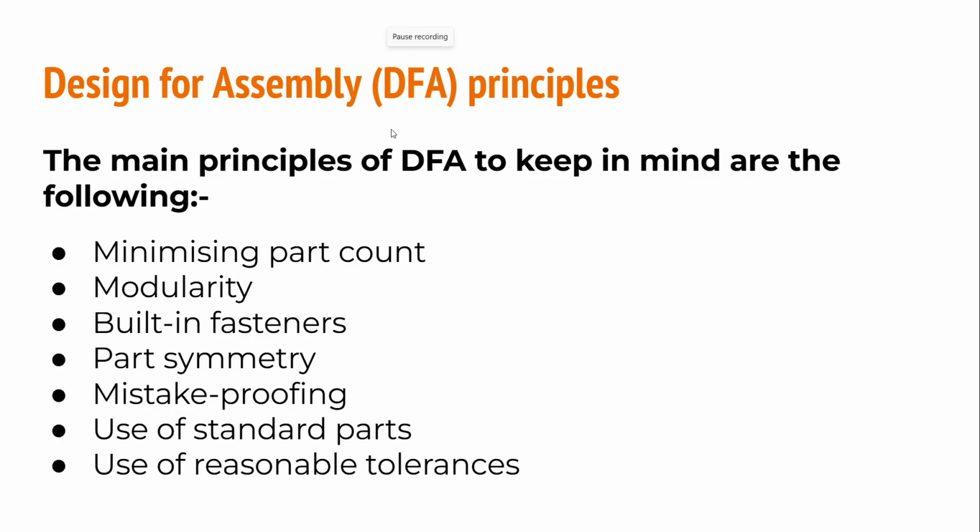Here is the design for assembly principles. These are some steps: minimizing part counts, modularity, building in fasteners, part symmetry, mistake proofing, use standard parts, and use a reasonable tolerance.